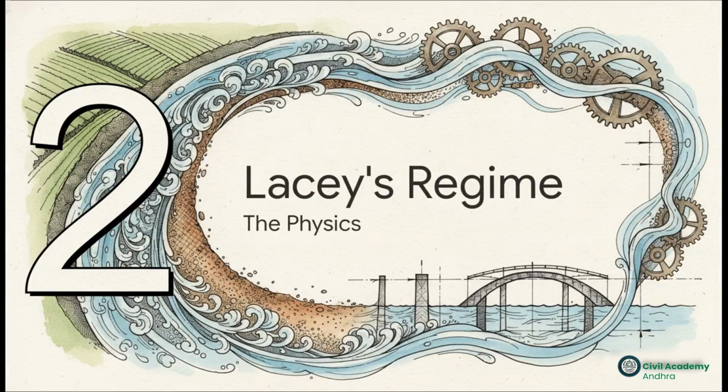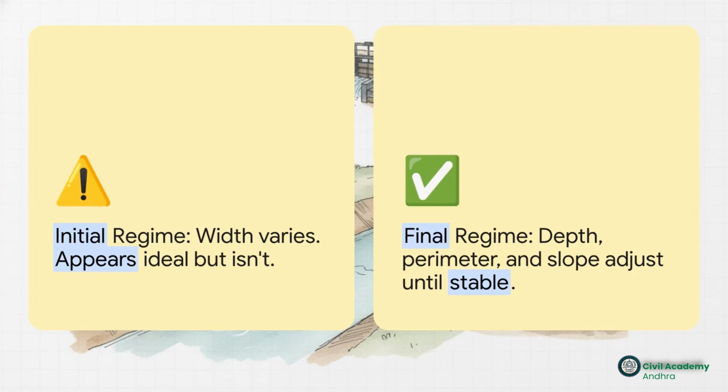Moving right along to section 2, Lacey's regime theory, the physics. Now that we know our required discharge, we've got to understand the physics of water interacting with unlined soil. Enter Lacey's regime theory. Gerald Lacey made this brilliant distinction regarding canal stability. He noticed the canals actually go through phases. First, there's the initial regime, where the canal might appear totally ideal, but it's deceptive because the width actually keeps varying. Then there's the final regime.